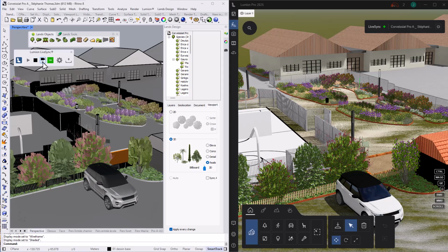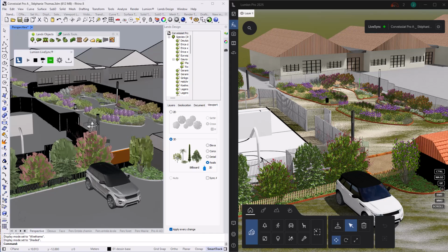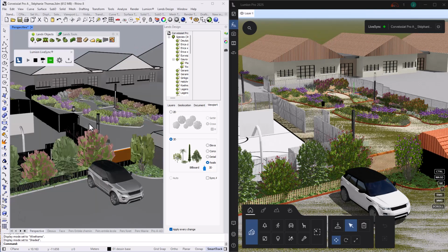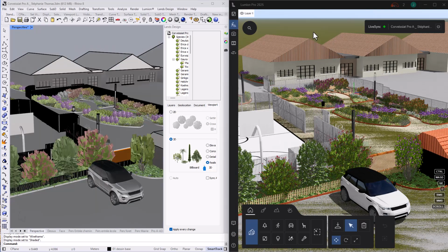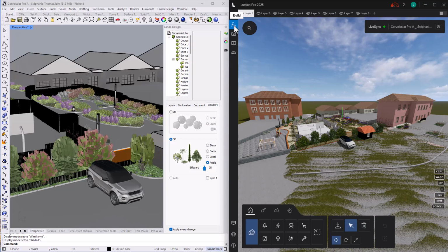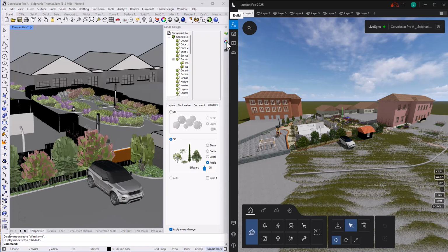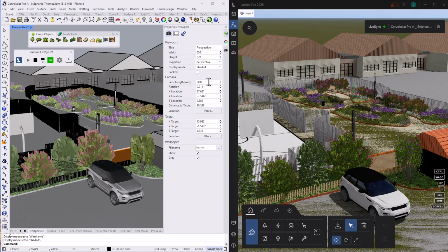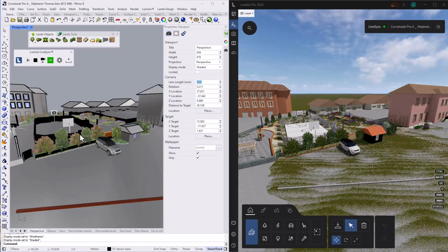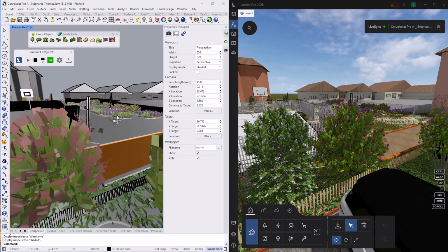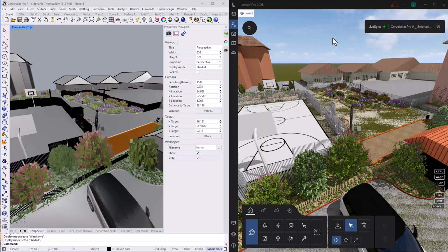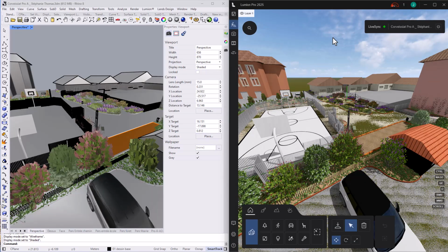When this button is activated, it indicates that the camera is linked. So when we control the camera movement from Rhino, those movements are reproduced in Lumion. If you notice that clicking inside the Lumion window changes the focal length, this happens because Lumion's build mode uses a default focal length of 15 mm. To match both views, we can adjust the focal length in Rhino's camera properties so they behave in the same way. Alternatively, we can click the button again to stop camera synchronization and work independently in Lumion.